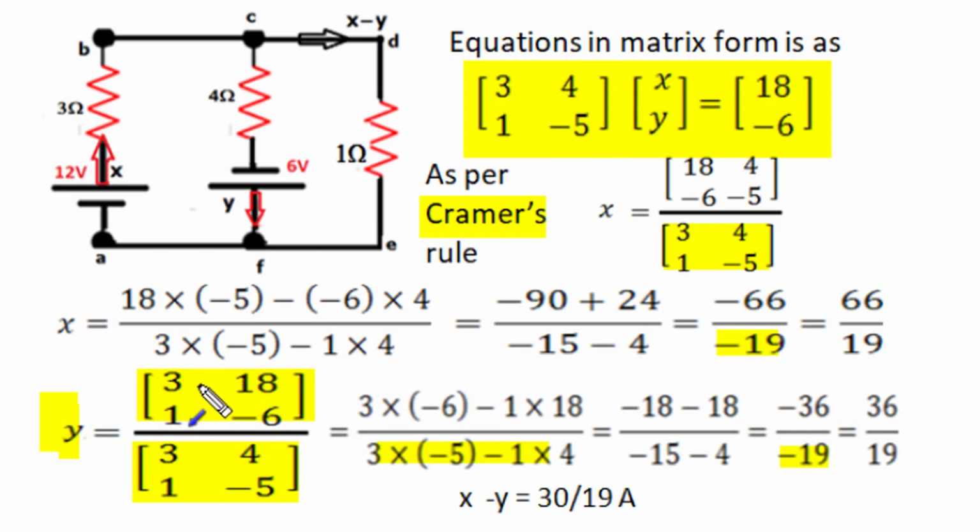For its determinant value, the diagonal elements are multiplied without sign change, and the off diagonal elements are multiplied and the sign is changed. So it becomes minus 18 and minus 18, minus 36, and when this negative of numerator and denominator are cancelled out, it becomes 36 by 19, and the positive answer indicates that the assumed current and real current are in the same direction, and the current of 4 ohm is 36 by 19.